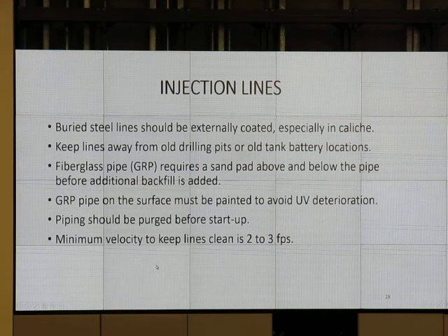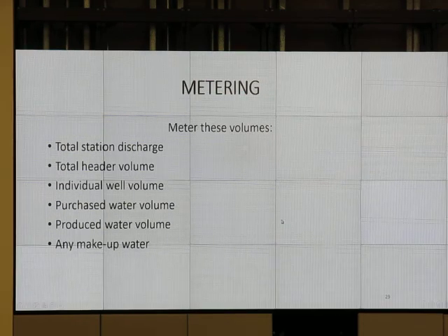And then here's a recommendation on minimum velocities to go through a pipeline so that we don't let solids accumulate in the bottoms. Let's keep it to a couple of feet per second to keep things moving as we go through. We'll catch it in filters or strainers. Metering.